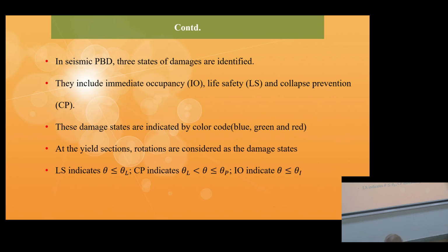Collapse prevention, the last one, means the structure will be heavily damaged. You have to run out. And whether the structure can be retrofitted, strengthened or demolished is a decision taken later. But it does not collapse as such, though heavy damage takes place.